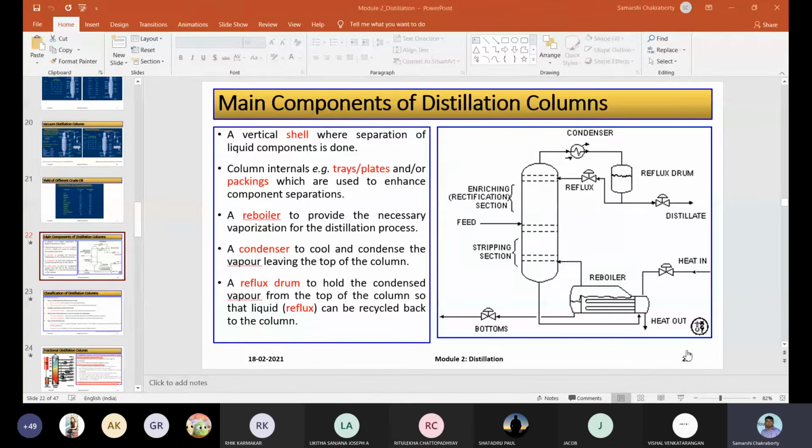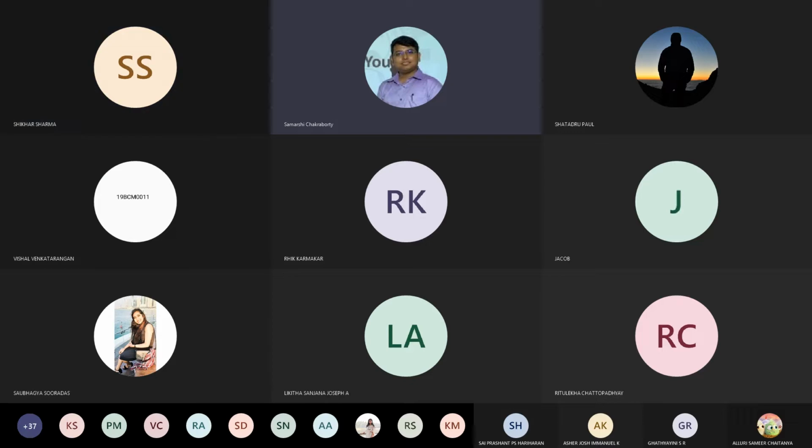The reflux rate is decreased. No, no, not that. The reflux rate is increased, yes, uncontrollably increased. And if the temperature is reduced, then what will happen? More condensation will take place. If more condensation takes place, then my liquid holdup is also increasing.